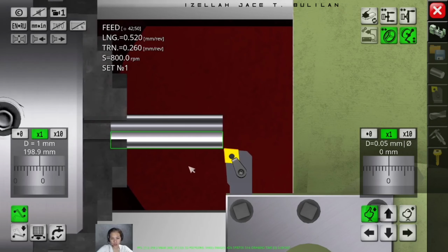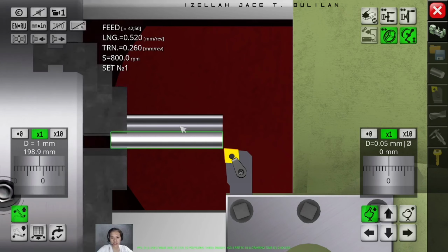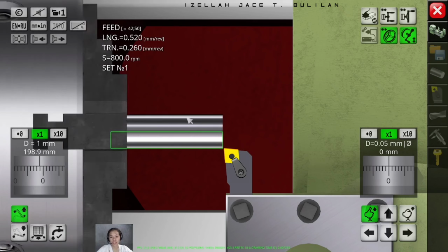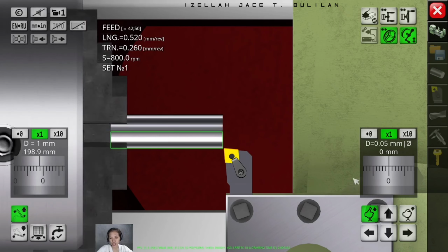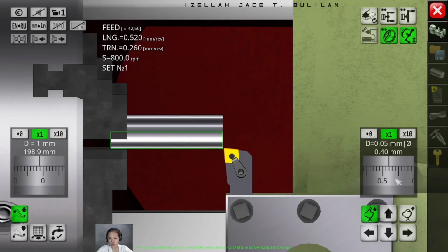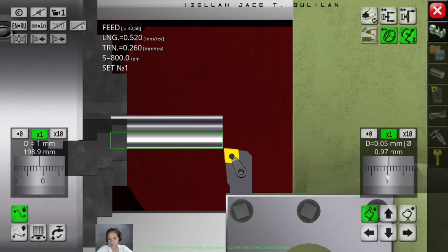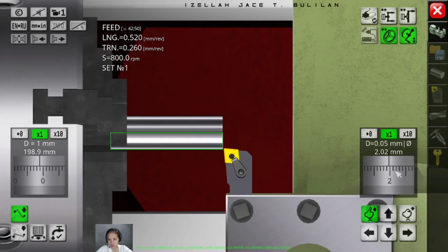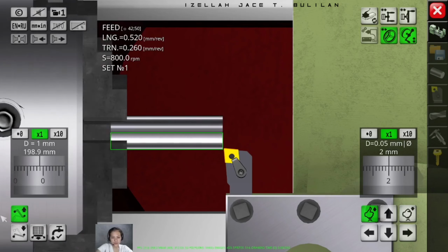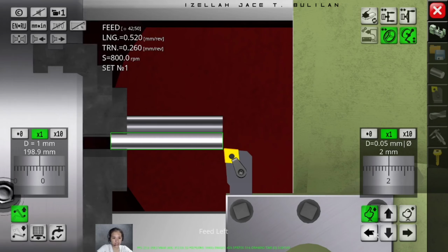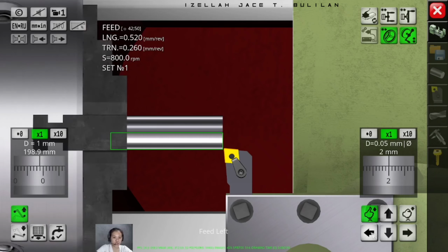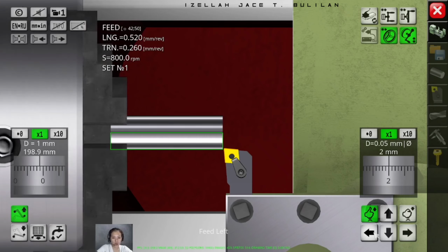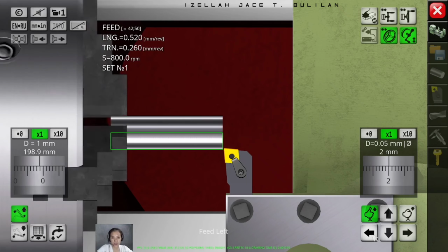So this workpiece material is 30 diameter, and we're going to reduce it to 28 millimeter based on the given dimension. So we're going to do 2 millimeters in here. And move the feed longitudinal movement up to 80 millimeters, but I'm going to make it 81 for a cleaner cut in facing operation.